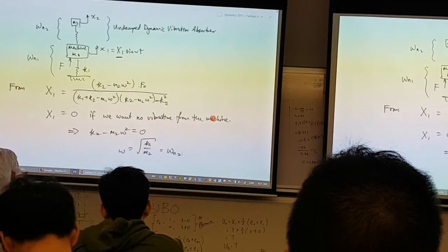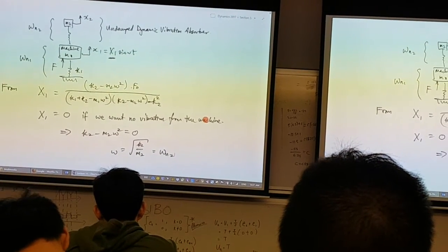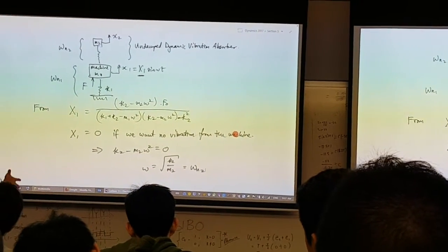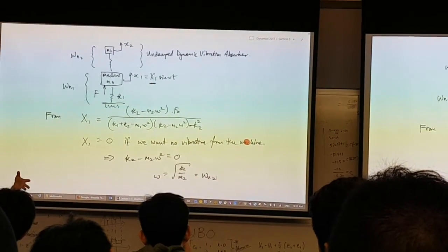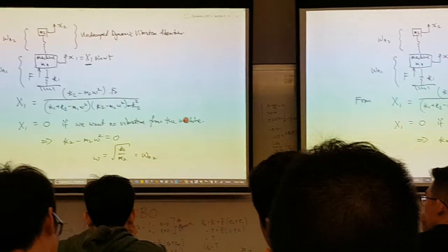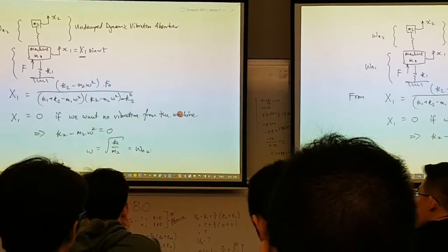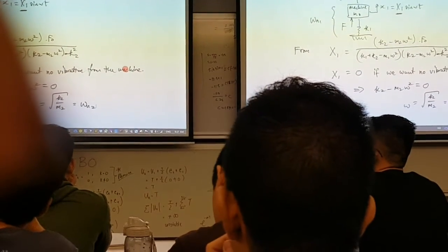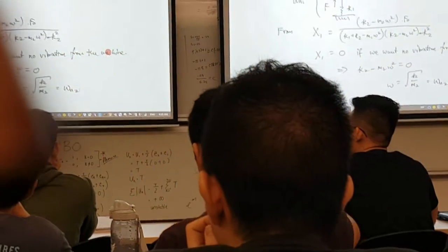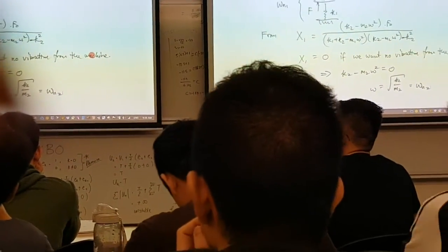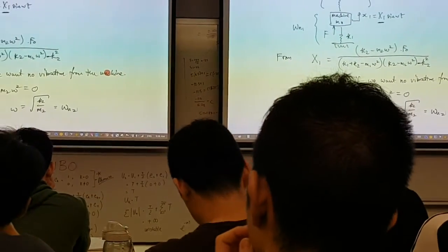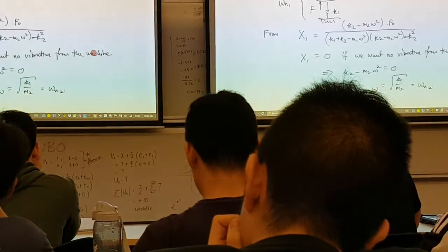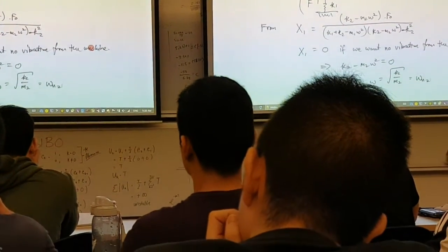So this is a very powerful thing. You convert a single degree of freedom system, that is your machine, into a 2-degree of freedom system such that the top part will resonate, bringing away most of the energy from the machine. That one would resonate. Maybe that one is just a spring and additional mass. And then you can stop your machine from resonating. That's a very powerful thing.